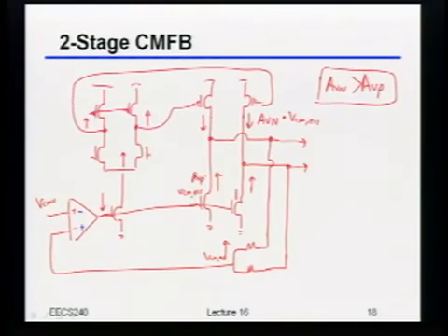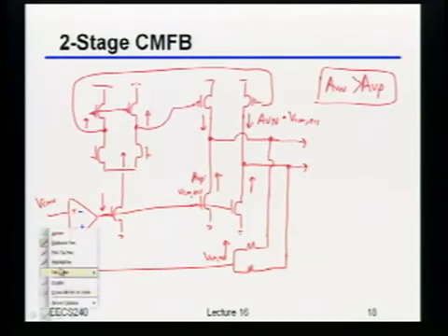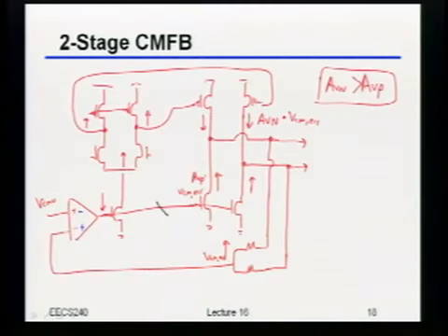Okay? So, other than walking through this whole loop analysis and things like that, any idea what we could do that would be a little bit better to make this whole thing work more cleanly? Or to avoid some of these? Bias the current separately for first and second. Okay. So what you're basically saying is, why don't we just break this darn feedback loop? And again, I'll do that in a different color. Maybe what we should really do is just not connect those currents together. Maybe we should have separate feedback loops for each one of those.